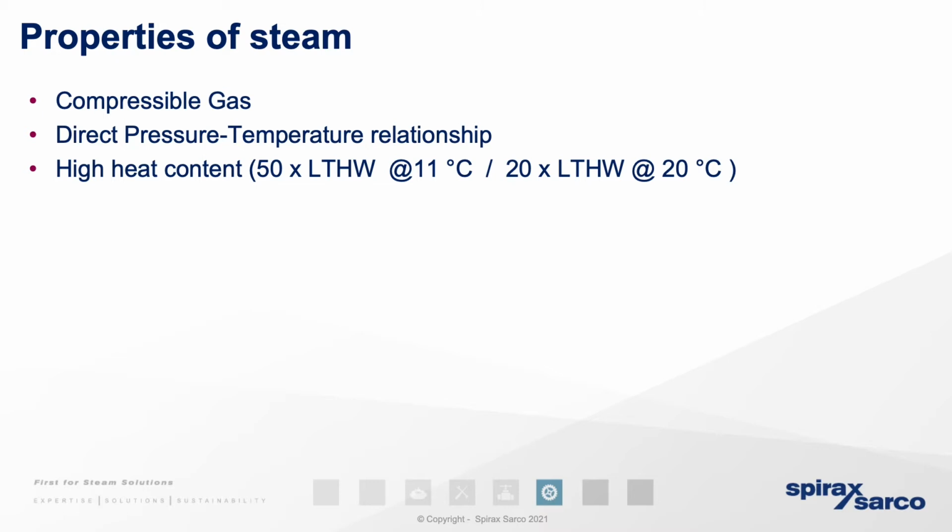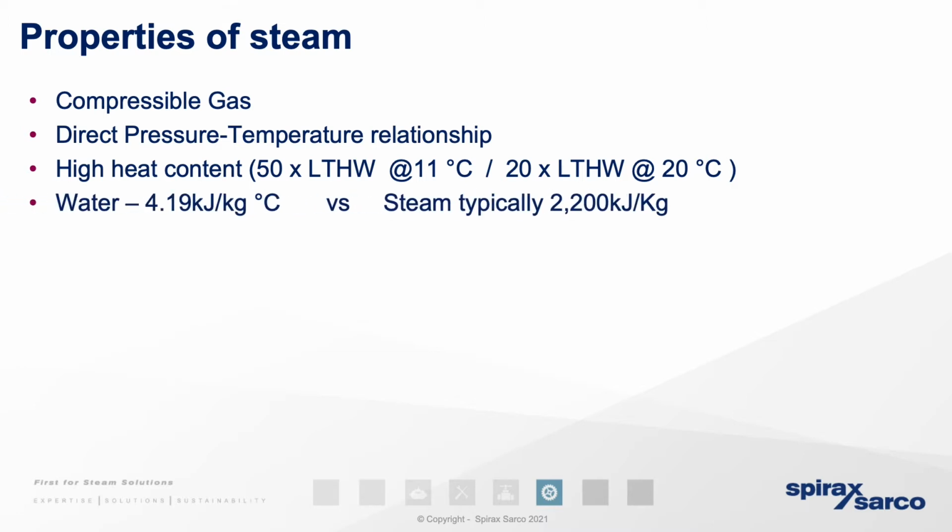We also know that steam has a very high heat density. The amount of heat energy we can deliver to the process is significantly higher than with a liquid-based system due to the latent heat energy contained within the steam vapour. Typically, that difference would be anything up to 50 times the amount of heat energy that we might find contained within, for example, a hot water system.